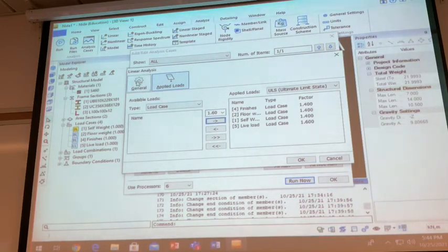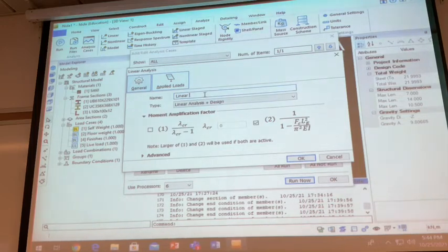And don't forget, you should name the load. Each analysis refers to each load combination, because you can check the load distribution from the corresponding analysis or the corresponding relevant load combination. So you should relate this one. It helps you to get the right solution for your design.